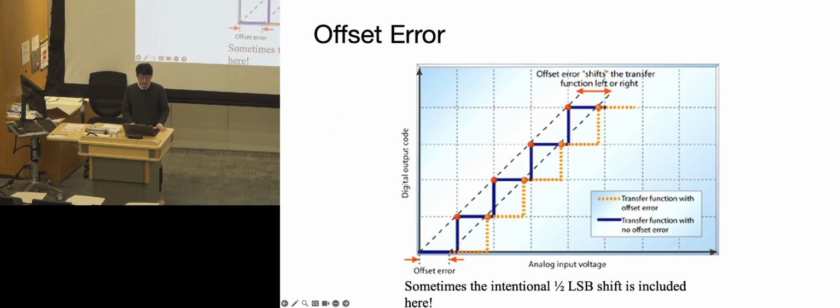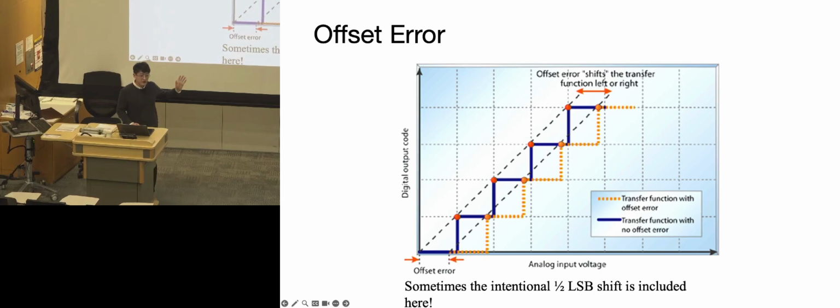We also have the offset error. Offset error is the deviation of the actual output voltage from the expected output voltage when the digital value is 0. It's something like what we just talked about, but you can think of it as a curve where the whole curve got shifted up or down. This is usually calibrated by having the system output digital 0, see what the output is on the actual pin, and then offset that value to all the future outputs. This is usually handled by the channels internally, and it's pretty easy to calibrate. Basically, STM already did this for you.